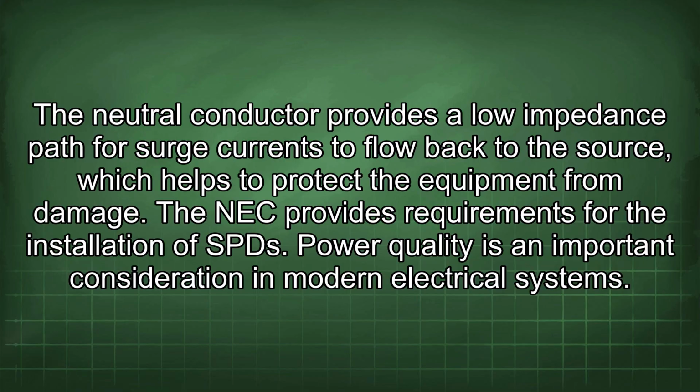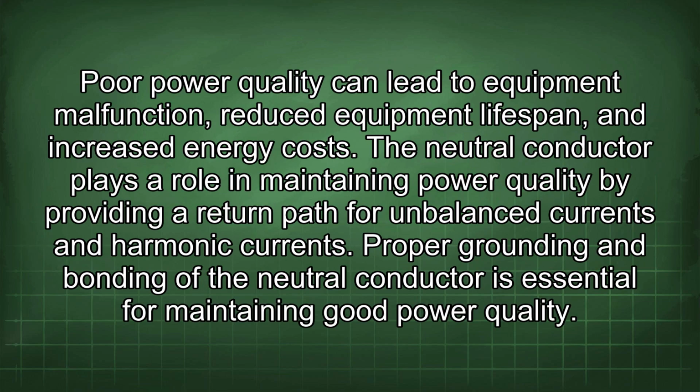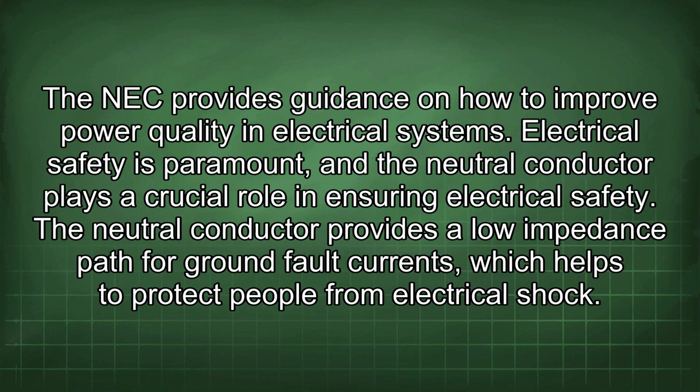Power quality is an important consideration in modern electrical systems. Poor power quality can lead to equipment malfunction, reduced equipment lifespan, and increased energy costs. The neutral conductor plays a role in maintaining power quality by providing a return path for imbalanced currents and harmonic currents. Proper grounding and bonding of the neutral conductor is essential for maintaining good power quality. The NEC provides guidance on how to improve power quality in electrical systems.